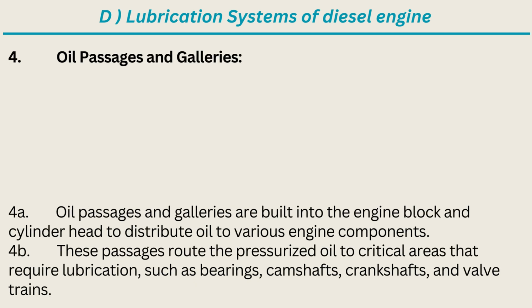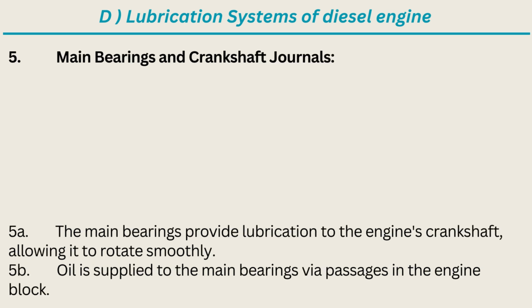4. Oil passages and galleries. 4a. Oil passages and galleries are built into the engine block and cylinder head to distribute oil to various engine components. 4b. These passages route the pressurized oil to critical areas that require lubrication, such as bearings, camshafts, crankshafts, and valve trains.